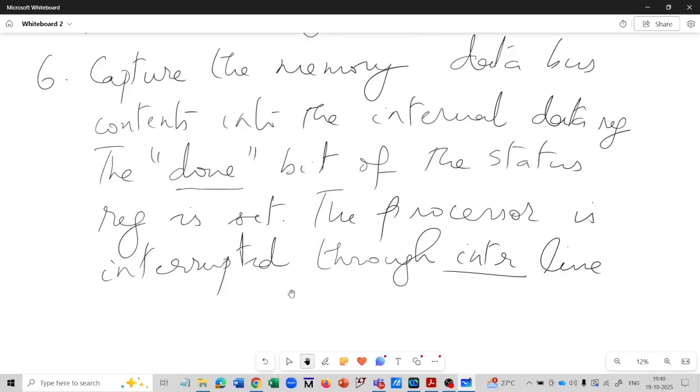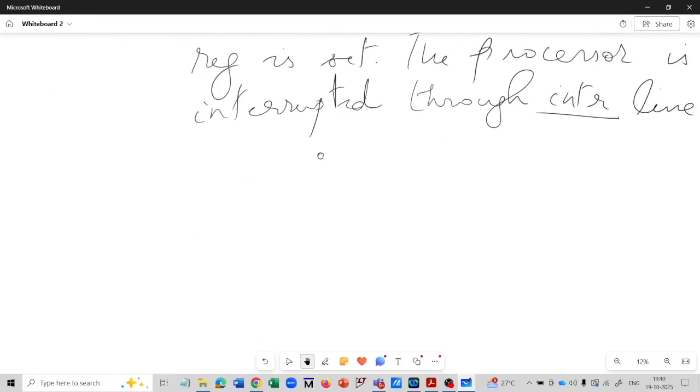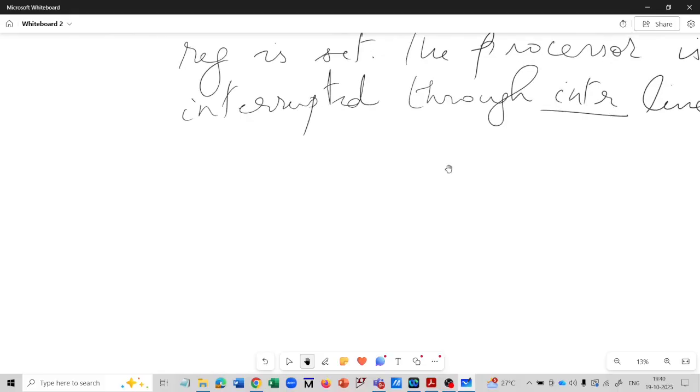The interrupt service routine is expected to read the status register to determine whether the transaction has completed, and it is also expected to read the data register to obtain the data that was fetched from the memory, which means that there are two subsidiary set of transactions that are also part of the functionality of the controller. That is the status register read and data register read.